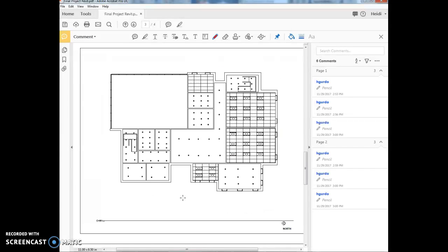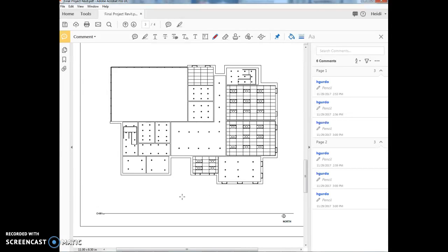Okay, that should be fine. For the ceiling plan, this is the first floor ceiling plan. To make the gypsum board hatch show up, I referenced your law office building book inside of the instructions. So you're going to want to go back to lesson 6 in the Revit 2017 Architecture Certification Exam Study Guide and look at ceilings, or you can go to the law office and check out section 6-4 ceiling systems, and they walk you through how to make that hatch show up.